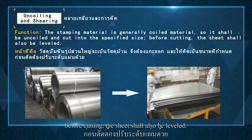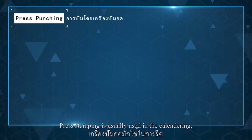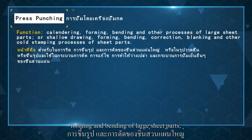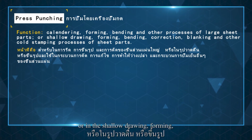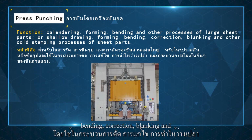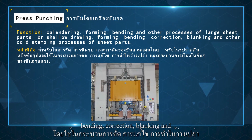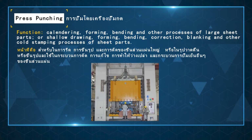Before cutting, the sheet should also be leveled. Press stamping is usually used in calendering, forming, and bending of large sheet parts, or in the shallow drawing, forming, bending, correction, blanking, and other cold stamping processes of sheet parts.